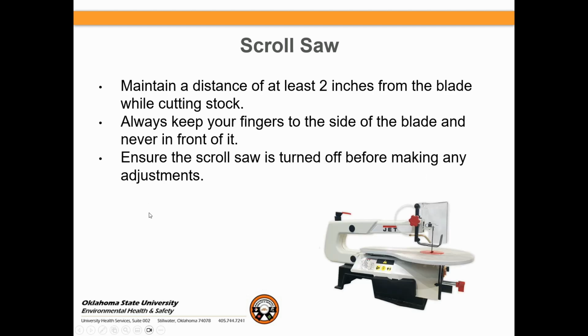Maintain a distance of at least 2 inches from the blade while cutting stock. If you're not familiar with what the word stock means, basically it's the material that you're using. Always keep your fingers to the side of the blade and never in front of it. Ensure the scroll saw is turned off before making any type of adjustments.